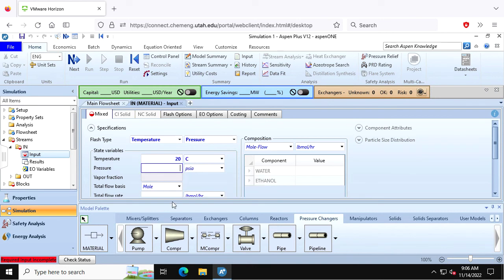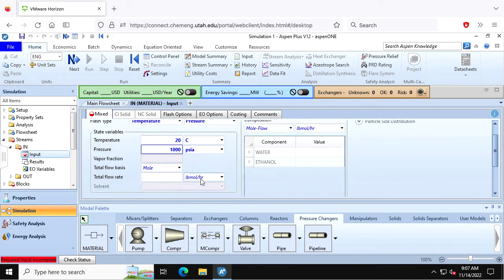So back to this, I'm going to put a high pressure. We calculated that just due to the rise, it would be about 55 psi, 55 or 60. But then there's pressure drop because of frictional losses through that pipe. So I will say, to use a round number, 1,000, which is way higher than it needs to be probably, but we'll leave it at that. Okay, so now when I put in 1,000,